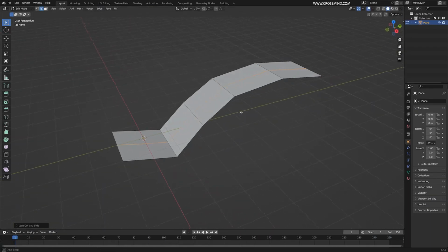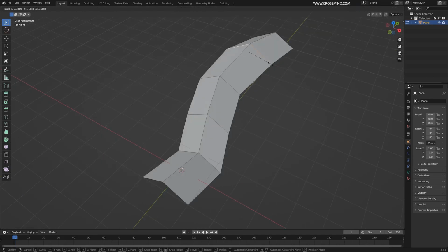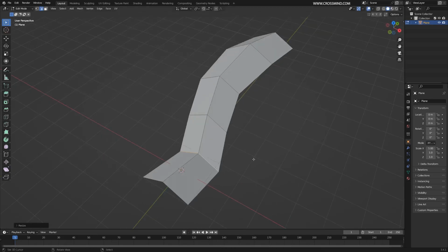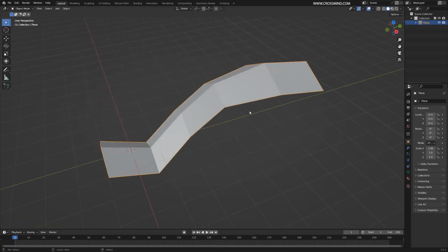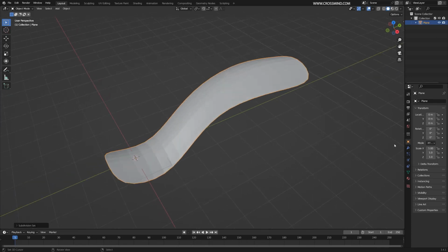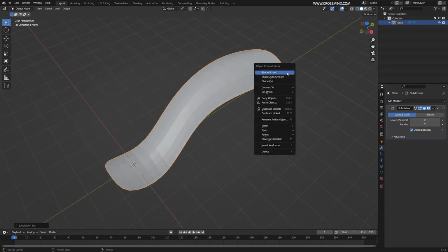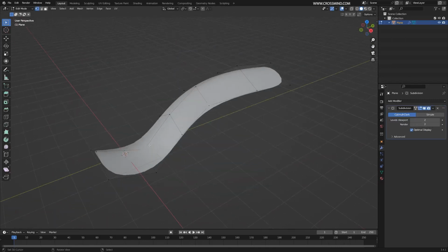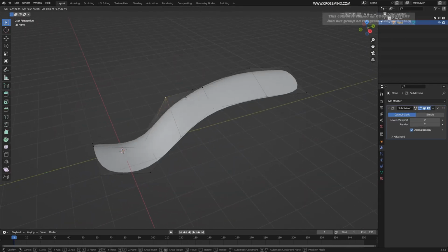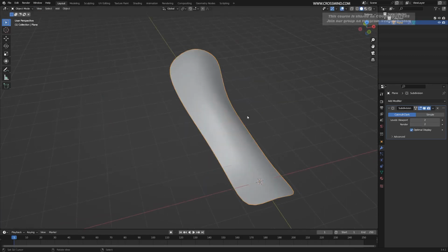So this low resolution model is quite easy to manage, to animate, render, and going to perform quite well. If I need to render this, I can apply a subdivision surface on this by pressing Ctrl 2. And this gives you a smoother surface, shade smooth. So this mesh, the main mesh underneath it, these points are there to control. This is what you control to model. But the smoother surface is what you use to render.